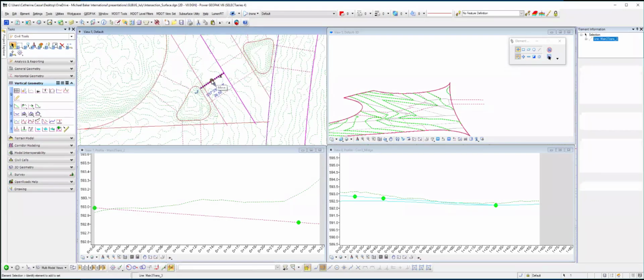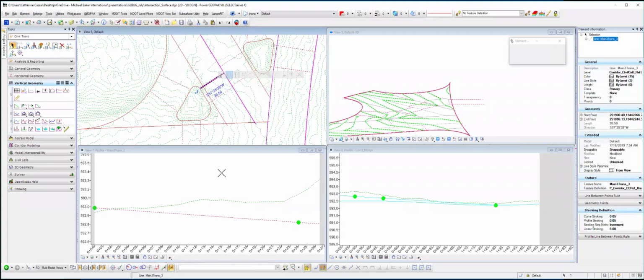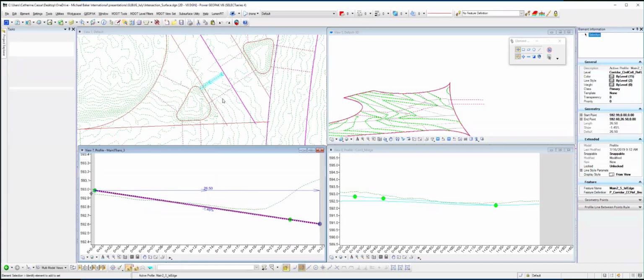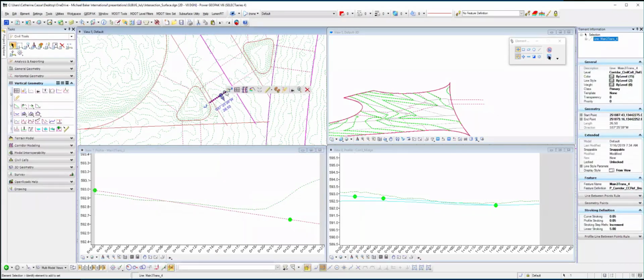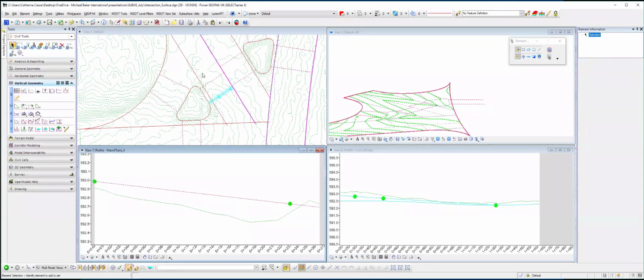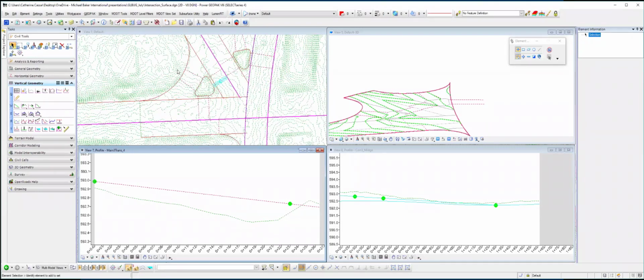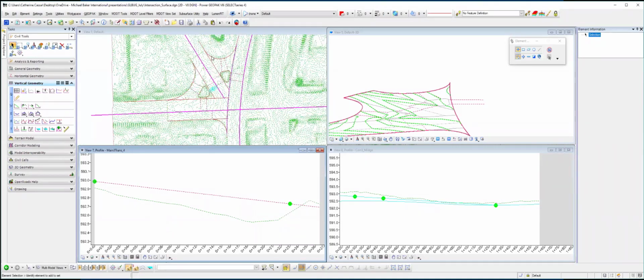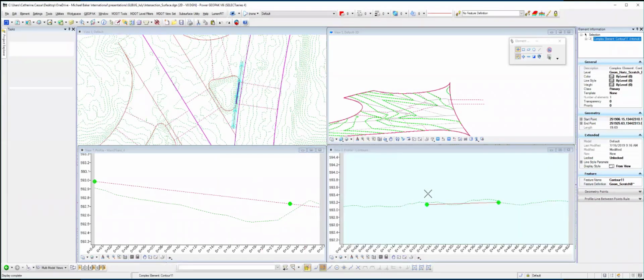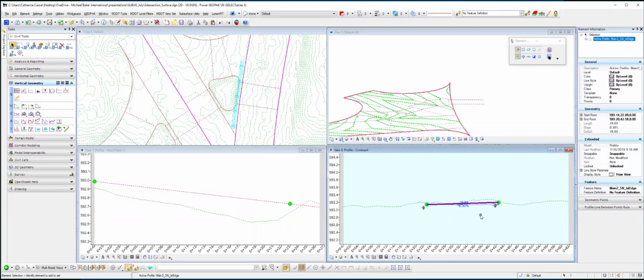And then likewise, same thing on this side, a similar approach with the warping. This is at 1.45. 1.1. So you can begin to see how you can manipulate this area of the pavement to make everything work. This is, like I said, always a good check to make sure my island is going to work on this side. And this is just a straight shot between these 2 points.